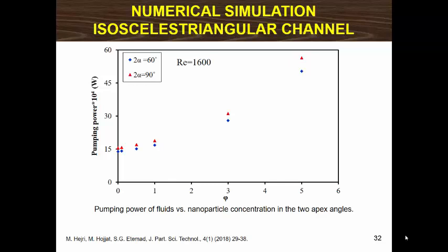Much research has been done on optimizing the composition of nanofluids and the equipment that uses nanofluids. I implemented multi-objective optimization to minimize the total pressure drop and maximize the nanofluid Nusselt number in a shell and tube heat exchanger according to the NSGA2 algorithm. An artificial neural network was developed to predict the thermal and hydrodynamic behavior of two types of Newtonian nanofluids used as coolant in a shell and tube exchanger.